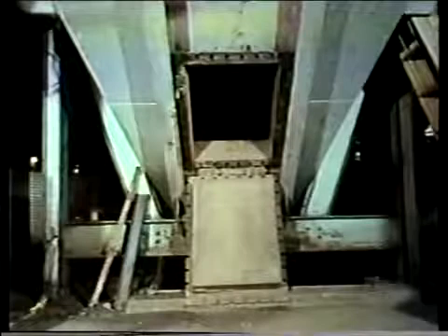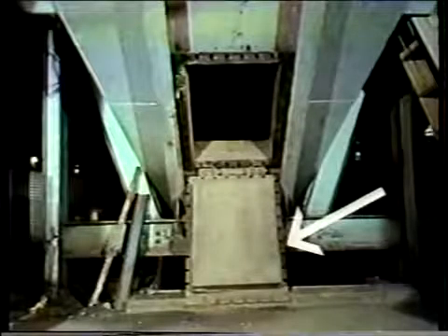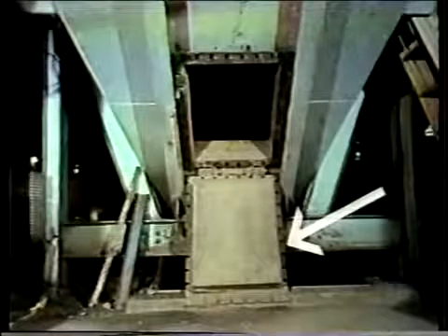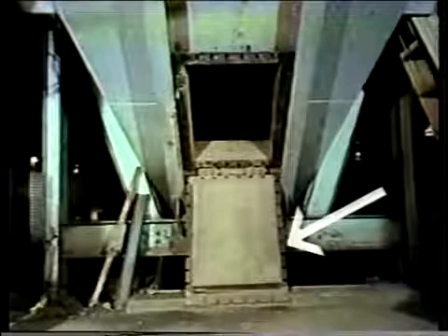Close and seal the access doors in the ash hopper area. Doors below the water level must be sealed so they'll hold water. Inspection doors with gaskets should be shut carefully to avoid damage to the gaskets. This is true throughout the boiler. Close the doors in the air ducts. If the doors were open to provide access to the water walls, they must be closed and sealed. Air ducts must be airtight in order to work correctly.